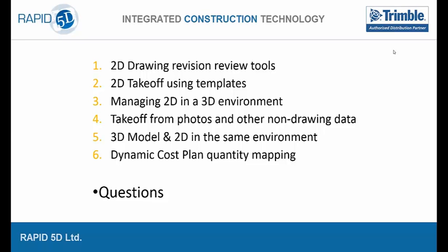Yeah, so we've got one actually. I think you noticed when I was spinning around that 3D model perspective. Vico Office does use perspective. We can switch that off in Vico Office so that we don't get that confused. So we can directly see on top of 2 different drawings. We don't get that weird perspective shift. So for anyone who's worried about that.